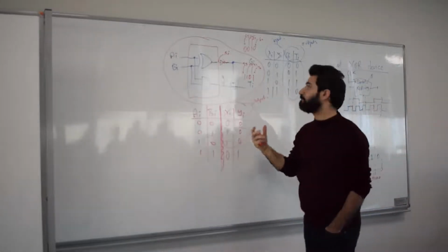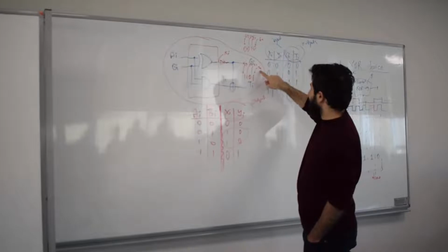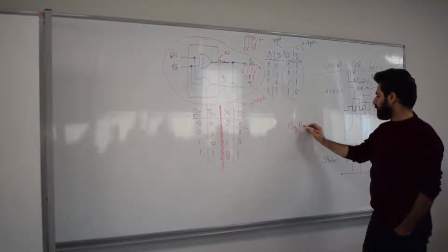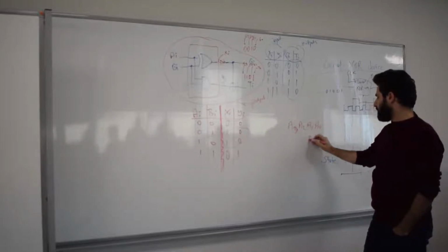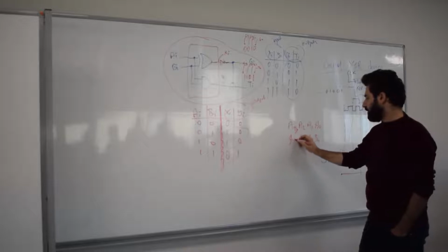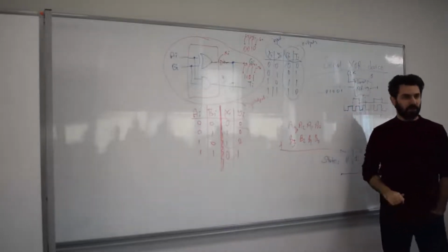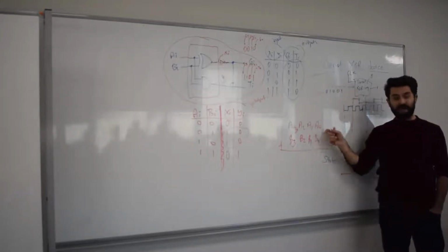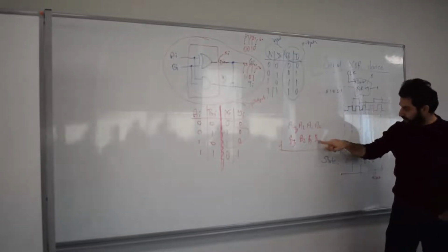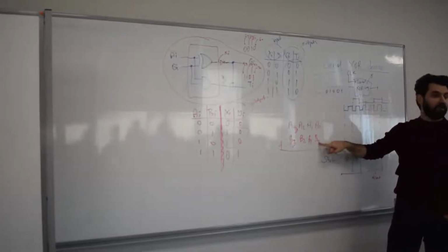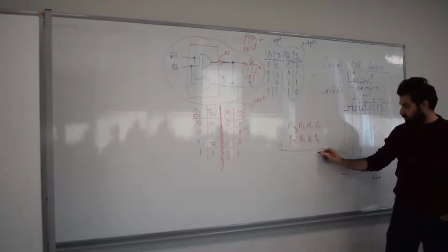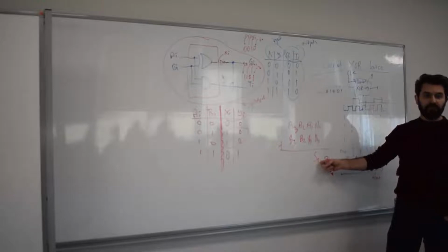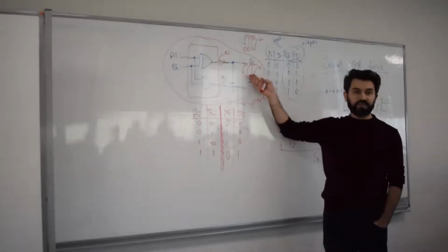What is that connection? If you got G0 and T0, and you'd like to add two numbers, like A3, A2, A1, A0 and B3, B2, B1, B0, that's what you want to handle. This is the main objective of the question. The question asks, what's the sum of A and B? So what you need is A0 XOR B0. That's your first sum, S0. But that is not available directly. You have to figure this out from this circuit.